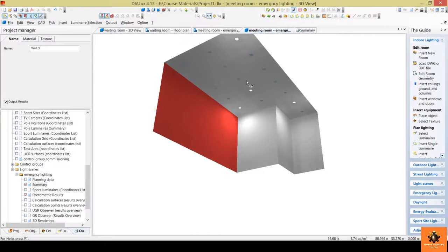Very good. But the important note here is that not in all cases will the percentage of the emergency luminaires be the same. As we said before, we use 25% of the luminaires to be energized or to be on at the emergency condition, but this 25% is not a constant percentage, as it depends on the nature of the room which we are working on. If the room which we are working on is not a critical one for its emergency design, we will use this 25%.